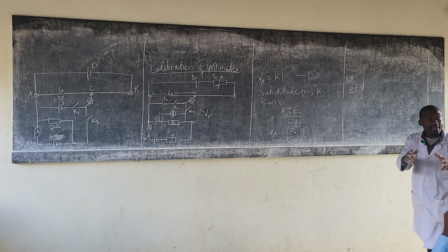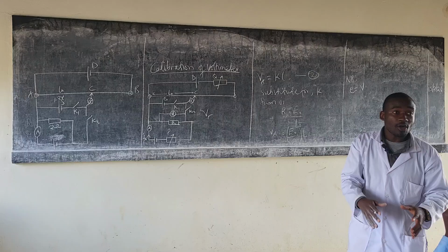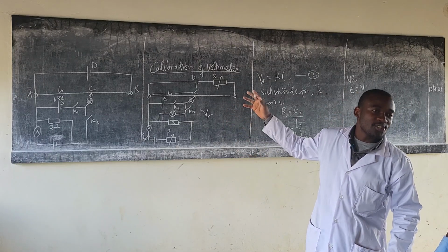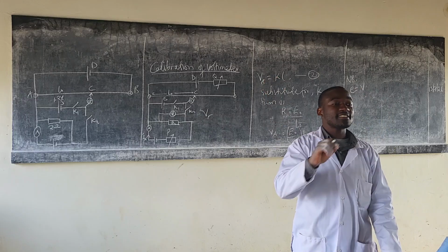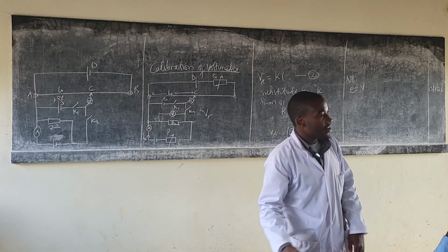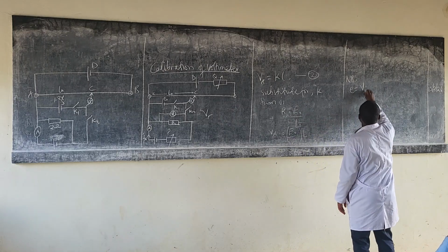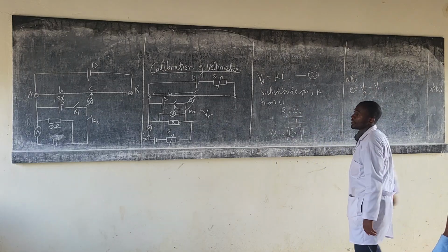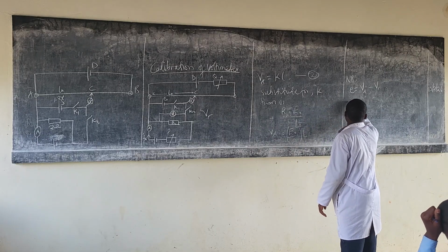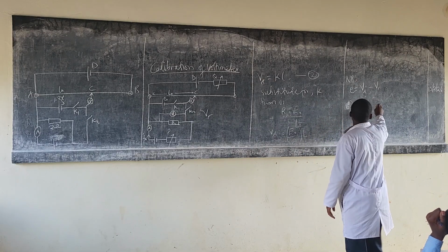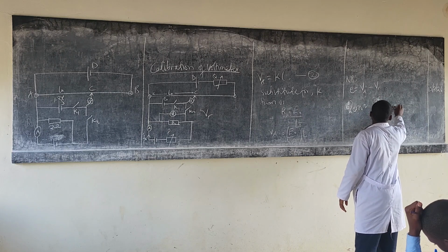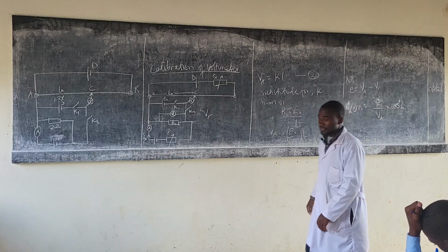So there is also an error in the voltmeter, because remember that before you close the switch and tap the jockey, you adjust a variable resistor for the voltmeter to give a smallest reading. So that error is going to be VA minus VR. And also the percentage error equals the error over the actual PD times 100%.